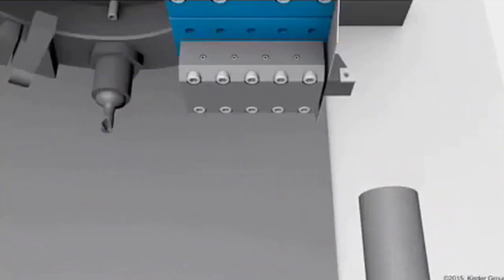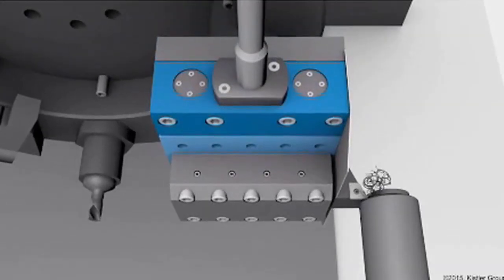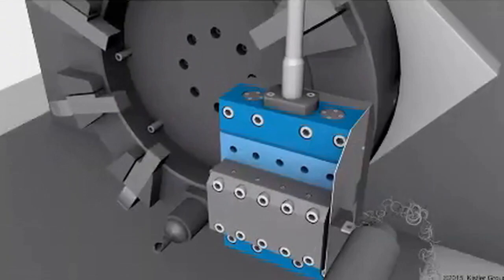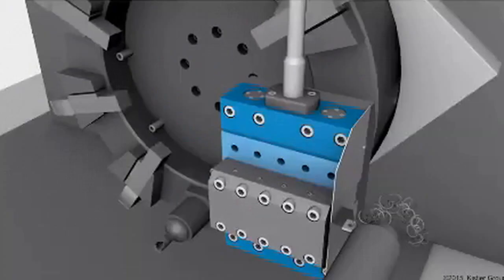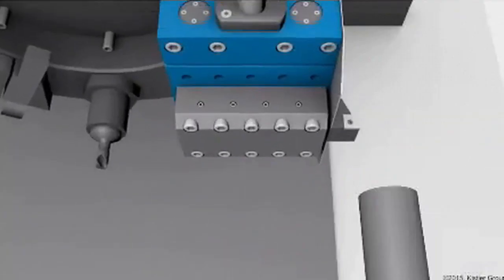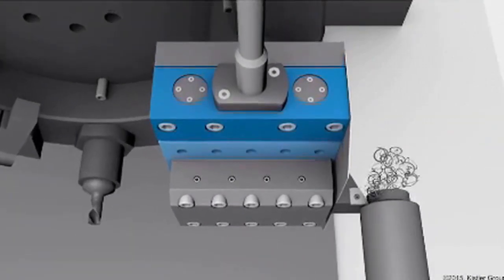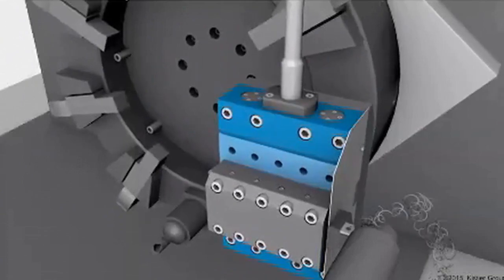So now as we are done with the milling machine, I just wanted to show you how it would look like in a CNC turning machine. Okay, so the dynamometer shown here is a static dynamometer because the tool is now fixed and the job, the workpiece, is the one that is rotating, right? So it's the static dynamometer, a piezoelectric dynamometer, on top of which we attach the tool holder with the insert, and the experiment is then conducted in the normal way as you would.